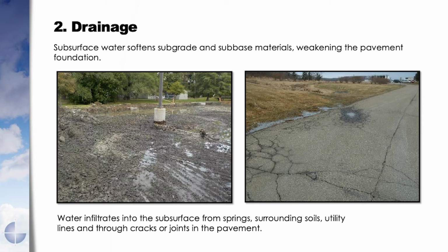Well, if you look beyond the pavement here, you can see water is sitting on the edge. There's not a real good ditch there. So poor drainage along the side of that roadway is allowing that water to soak underneath the pavement, soften up the base and the subbase, subgrade. And then as traffic goes over it, it cracks the pavement, allowing more water to go in.